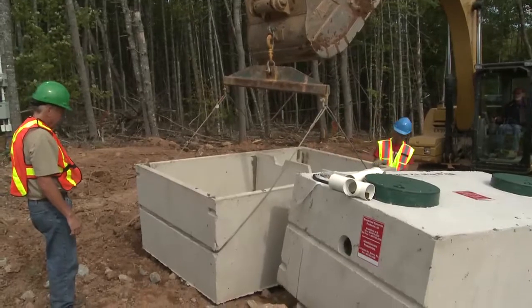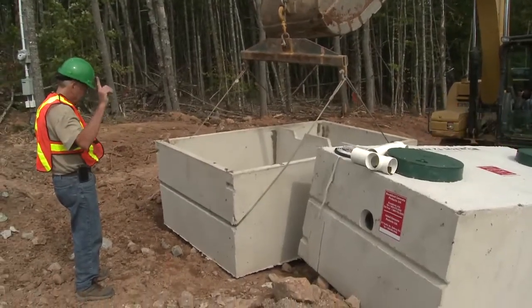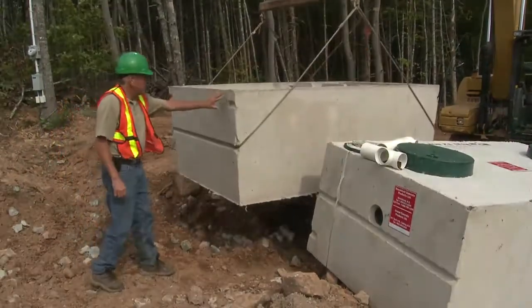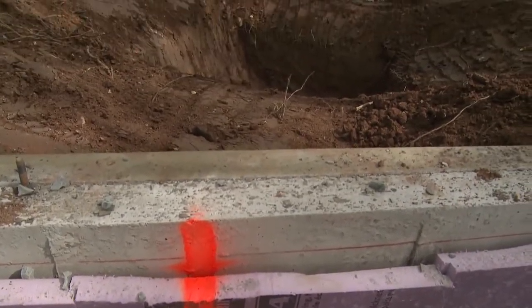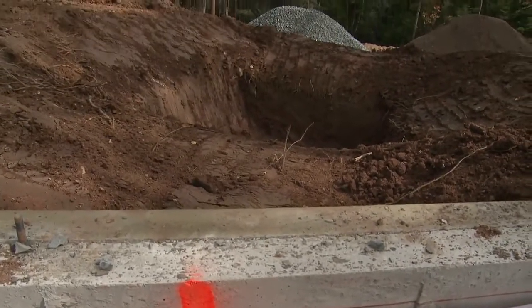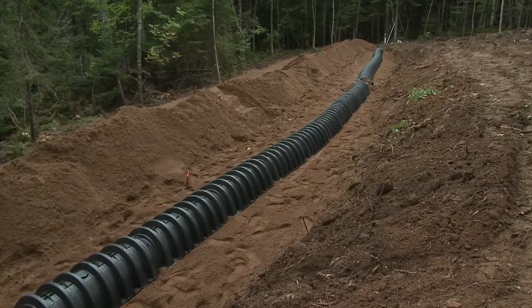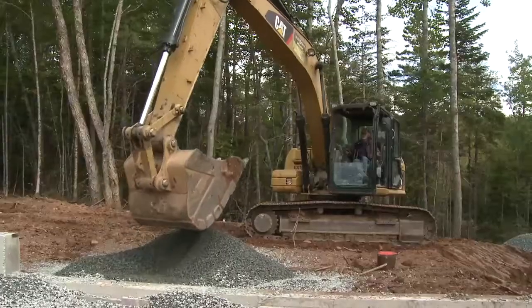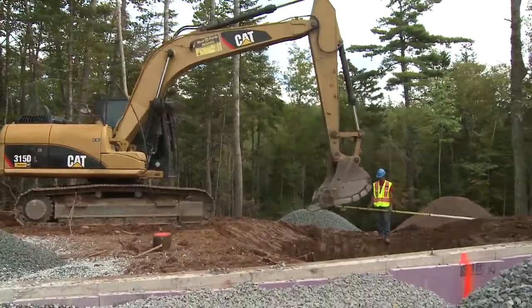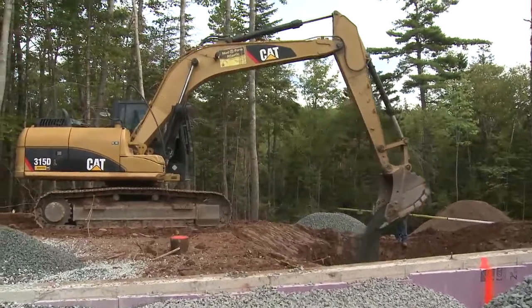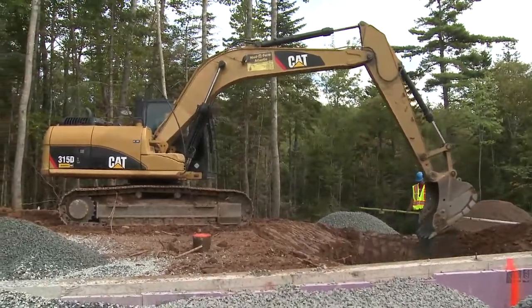An approved septic tank sized according to the approval will now be installed, allowing for a minimum of 2% slope on the pipe from the house to the tank and a minimum of 1% slope on the pipe from the tank to the bed. Minimum separation distances from the septic tank must be kept in mind, including 1.5 meters from the foundation drain.